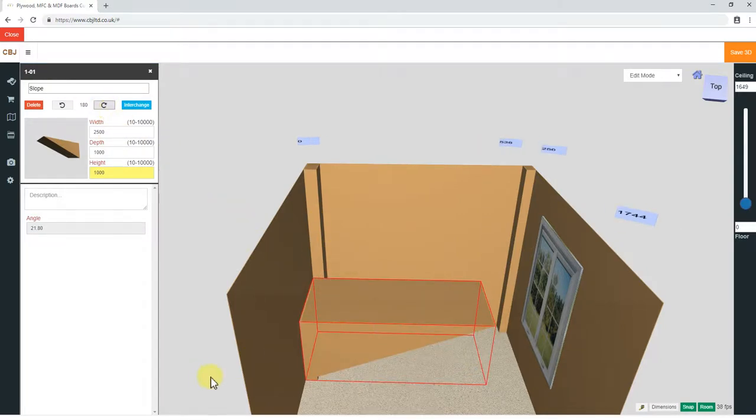Now, the crucial measurements, in order to set up what we need, imagine this is our room. As a normal site survey, we would require measurements A. I would need a straight line going down here, so I could measure the distance of the slope, which would be measurement B, and overall floor to ceiling height, which would be, say, C.